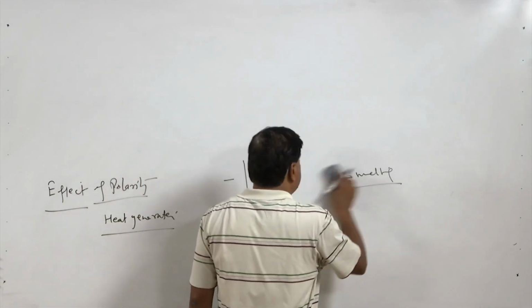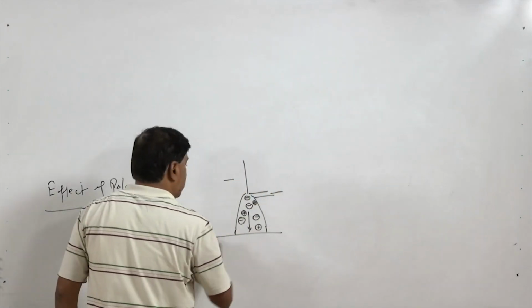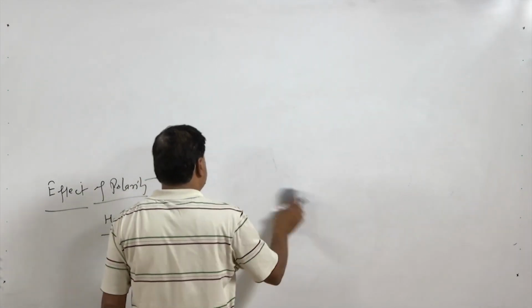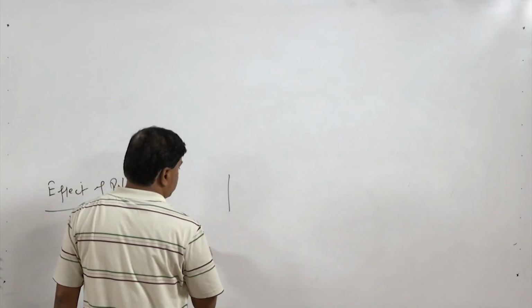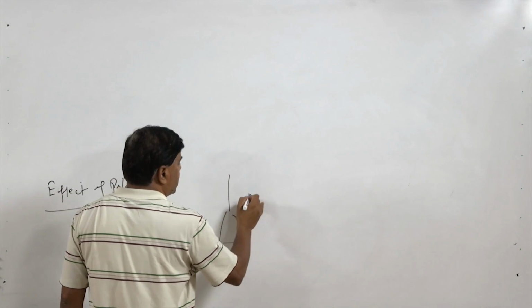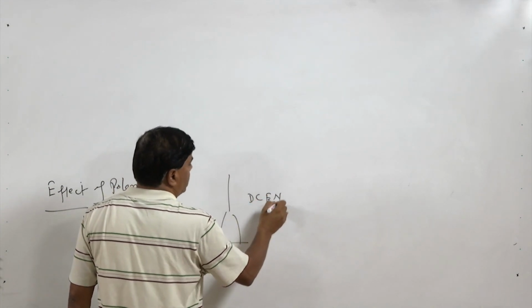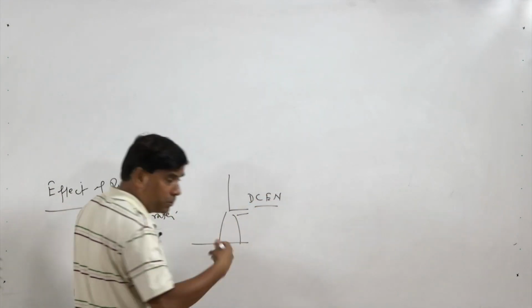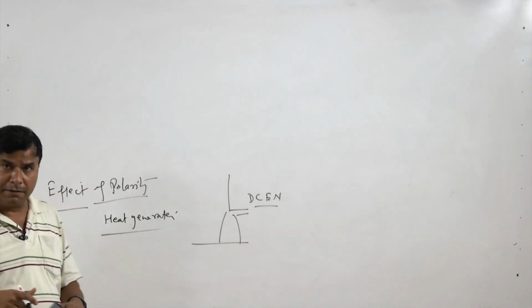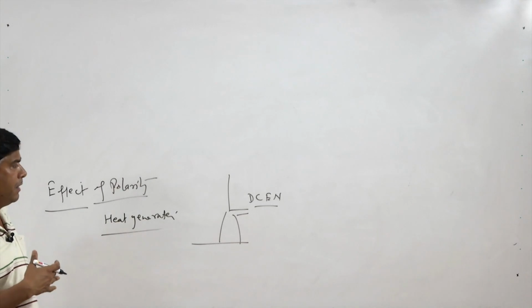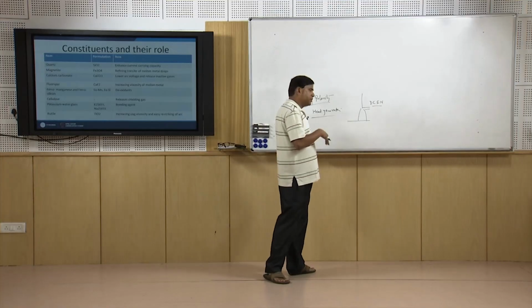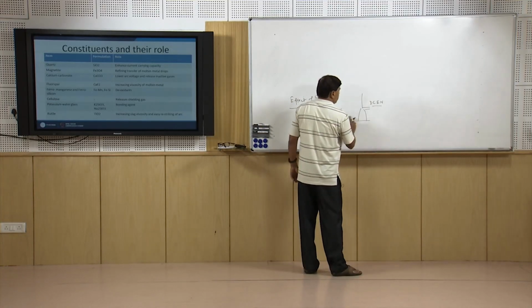So, to take this advantage in case of the tungsten arc welding, to have the much better life of the tungsten electrode, invariably the tungsten arc welding process uses the DC-EN polarity, so that heat generation in the electrode side is very limited. It leads to the much lower amount of thermal damage to the electrode, and which in turn results in much better electrode life.